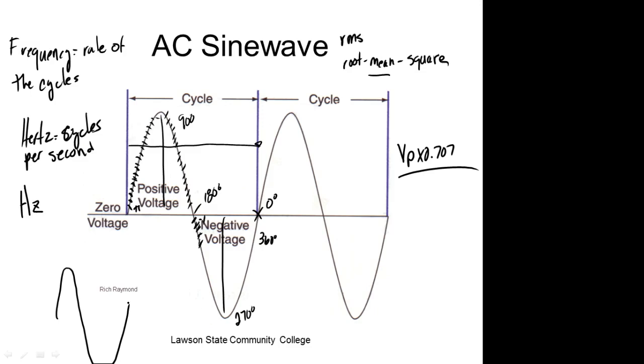So we say true RMS? They're very expensive. They actually have a microprocessor inside that calculates the root of the mean of the squares. And it should say true RMS on the faceplate somewhere. Yeah, so you've got a true RMS meter. Have you ever really needed true RMS? Probably not.